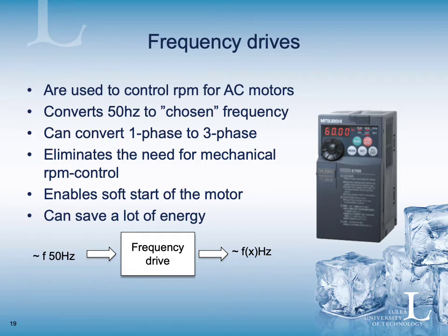Also, if you have an electric vehicle or something that is controlled by a battery, it's basically the same, but instead of feeding it with one phase or three phase, you feed it with a DC current. So the principle is the same, but you don't need the first part of the frequency drive. And the next slide will show how the frequency drive is built up.